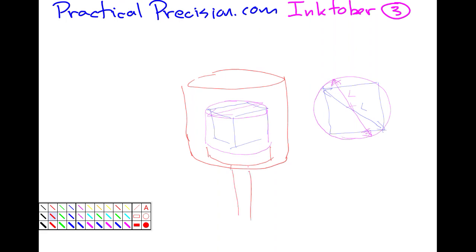It's rotationally symmetric about any segment theoretically. So it's really easy to do such things as break it up into 120-degree segments and use kinematic mounting. The heat flow, heat distribution, will generally be nice and uniform. I mean, you might get temperature differentials, but again, they'll be at least concentric.